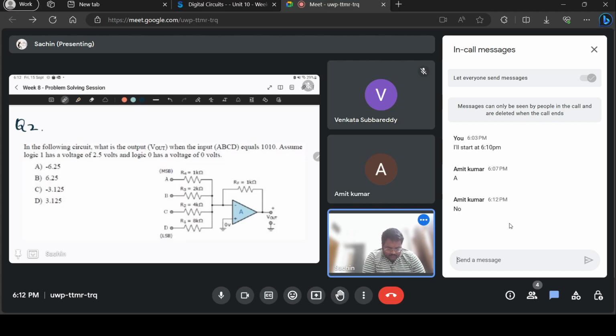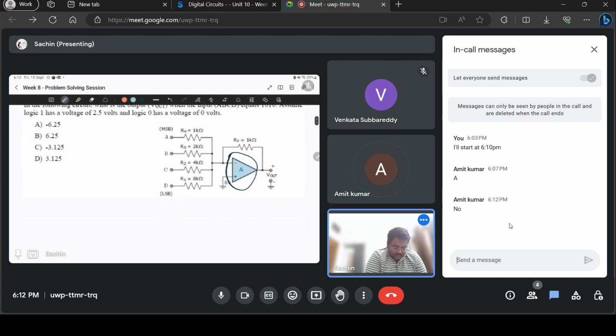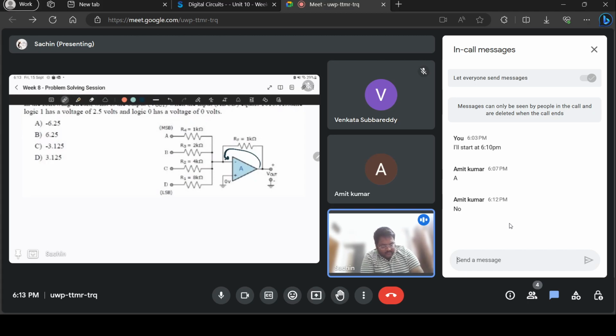See, one thing to know about an operational amplifier. This thing is called an operational amplifier, and when it's used in this way, it's actually used as a comparator circuit. Here, when you connect the output, you can see that this output is connected back to one of the inputs. When it is connected to the input labeled with the minus sign, the negative input, that is called negative feedback. One thing to notice about this.